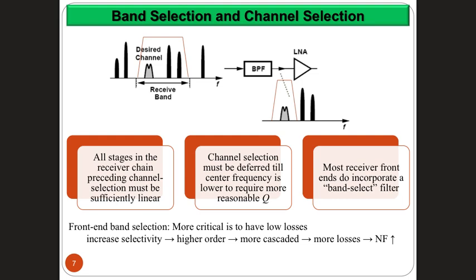It includes multiple channels, all of them within the band reserved for the GSM operator. So in this case, we can have a wider bandwidth, which allows us to get a reasonable quality factor at a center frequency of that GSM band, which is at 900 megahertz that we were talking about. So we only need in this case to make sure that we don't go into the band of another technology.